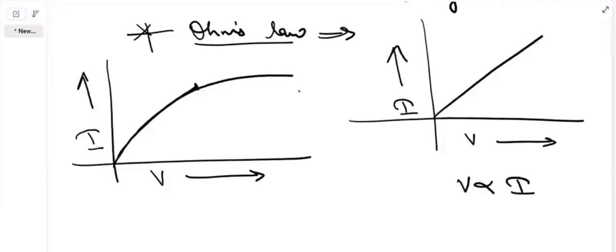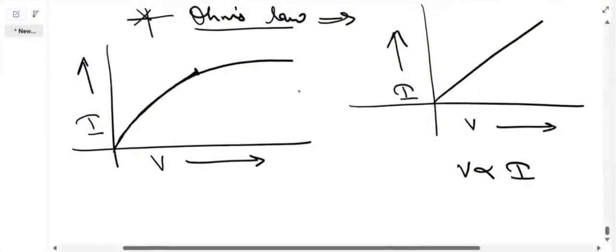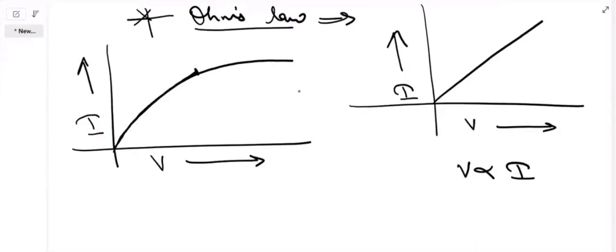The reason behind this is, if I take the example of the light bulb filament, the current flows through the bulb and electrical energy is transferred to thermal energy. This results in an increase in temperature, and it leads to an increase in resistance. Understood? Yes, ma'am. Hence they are not following Ohm's law, and ultimately they will become stabilized after a certain limit of time and show you a straight graph. Any doubts? No, ma'am.